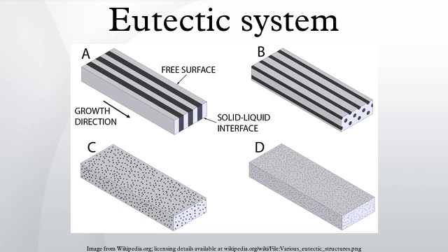A eutectic system, from the Greek "eu" and "tektos", describes a homogeneous solid mix of atomic and/or chemical species, forming a joint super-lattice by striking a unique atomic percentage ratio between the components, as each pure component has its own distinct bulk lattice arrangement. It is only in this atomic molecular ratio that the eutectic system melts as a whole, at a specific temperature, the super-lattice releasing at once all its components into a liquid mixture.